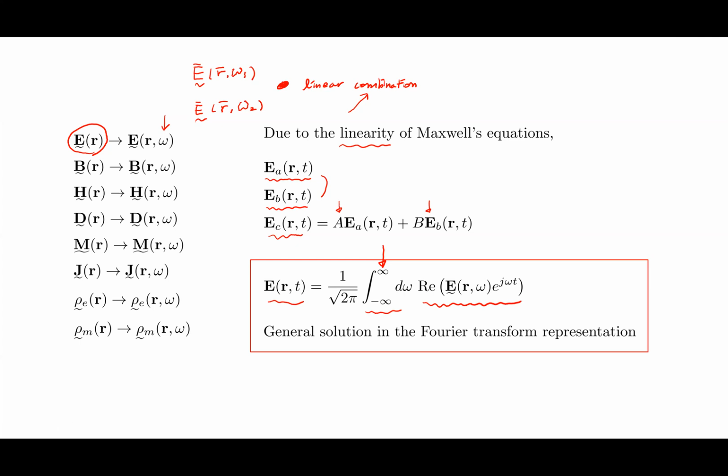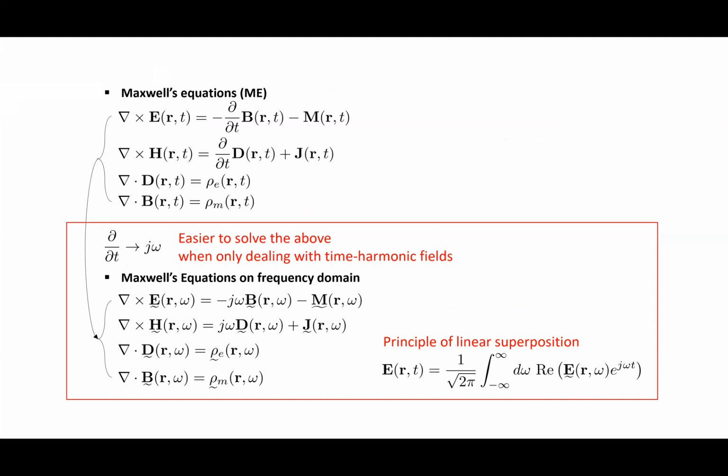Then the next topic is the overview of the frequency domain analysis again. Because it is difficult to solve the original Maxwell's equations due to the time derivative intertwined with the spatial derivative term, we can reduce the complexity of the problem by assuming that fields are time harmonic.